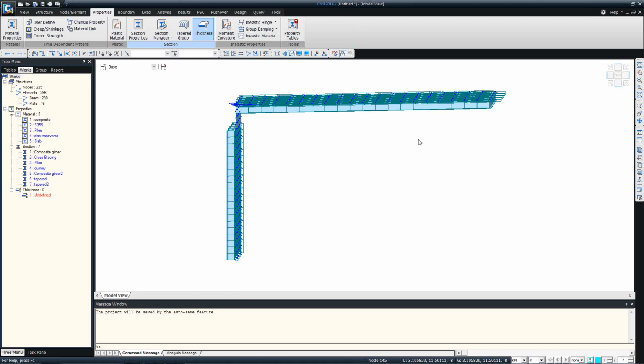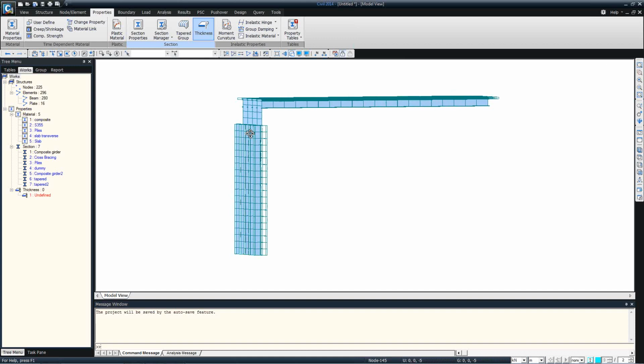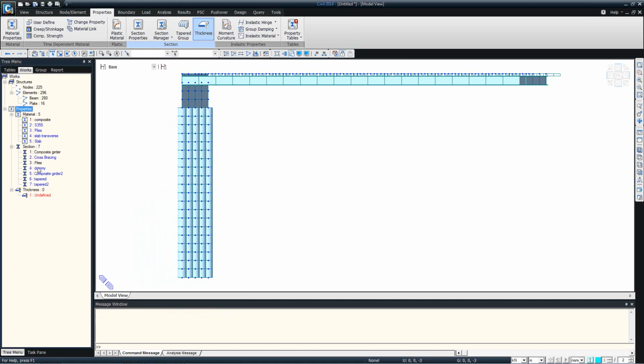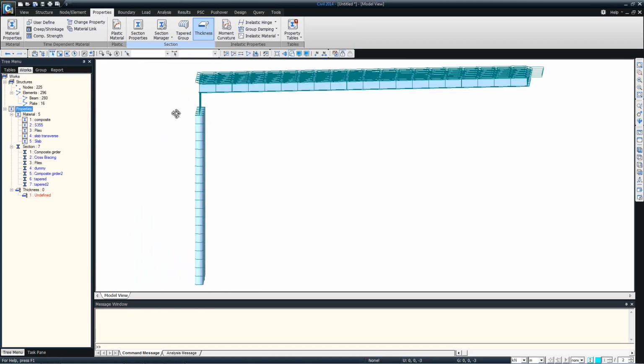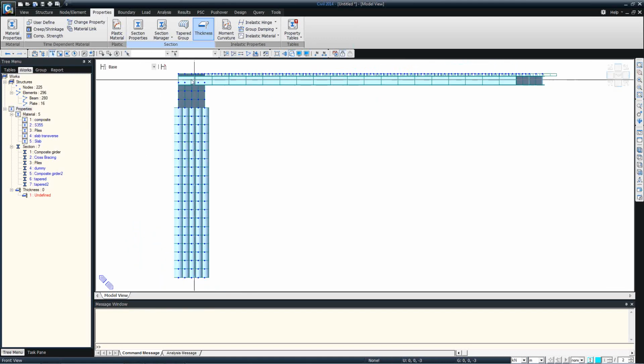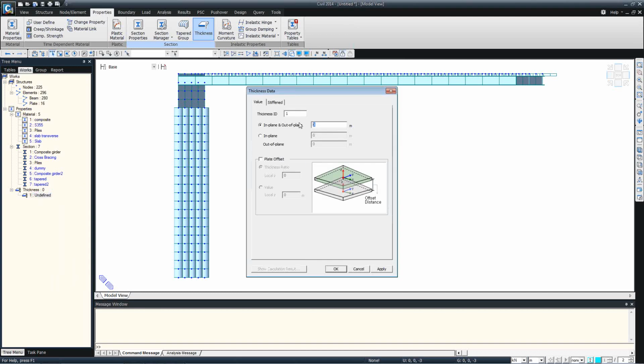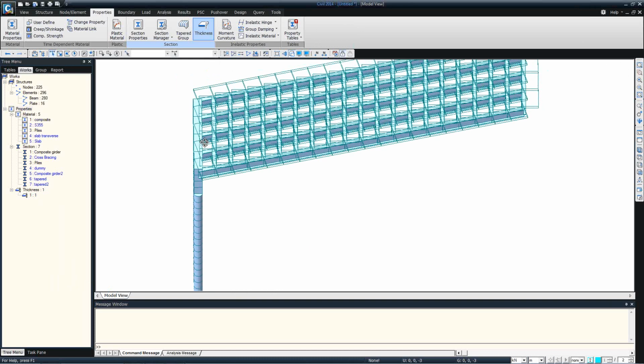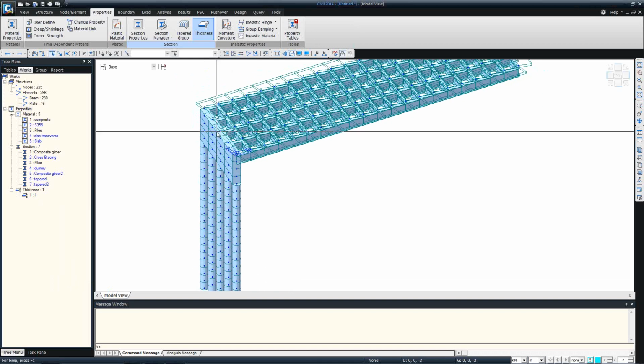Okay, I will now go towards assigning the properties correctly, because everything has been assigned with the composite section. Here we just have to select the correct elements, drag and drop piles, double click on piles again, drag and drop pile materials. Similarly for the abutment, make sure that everything is the abutment material. I haven't defined any thickness for the abutment, so I'll just define 1 meter as a thickness, and that's how we define the abutment and define the sections and the materials.